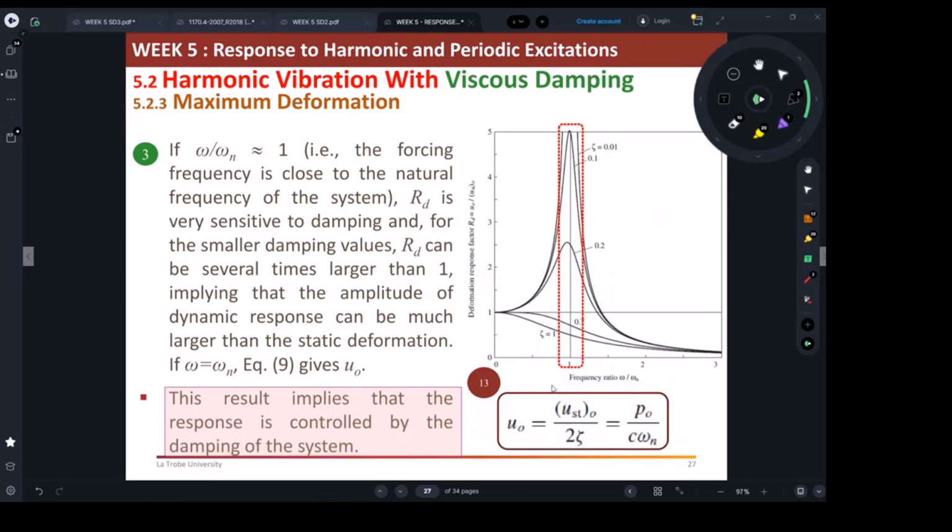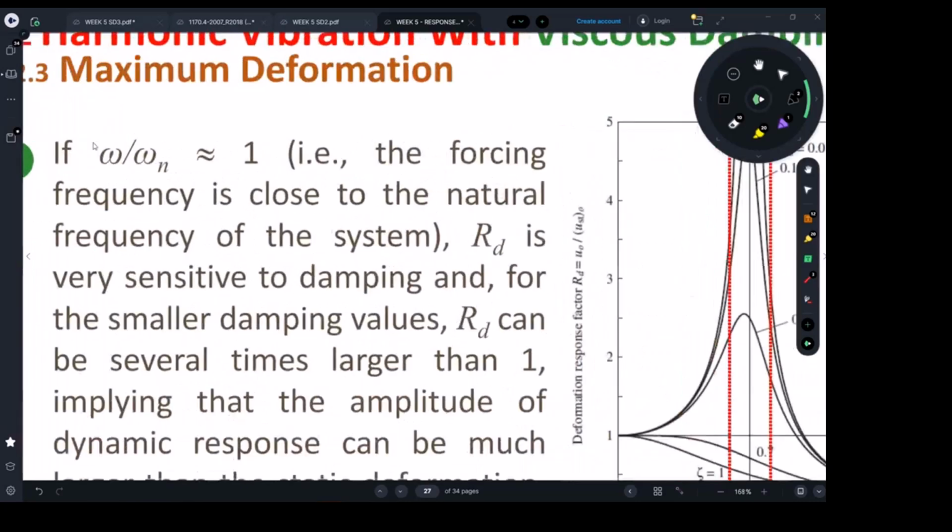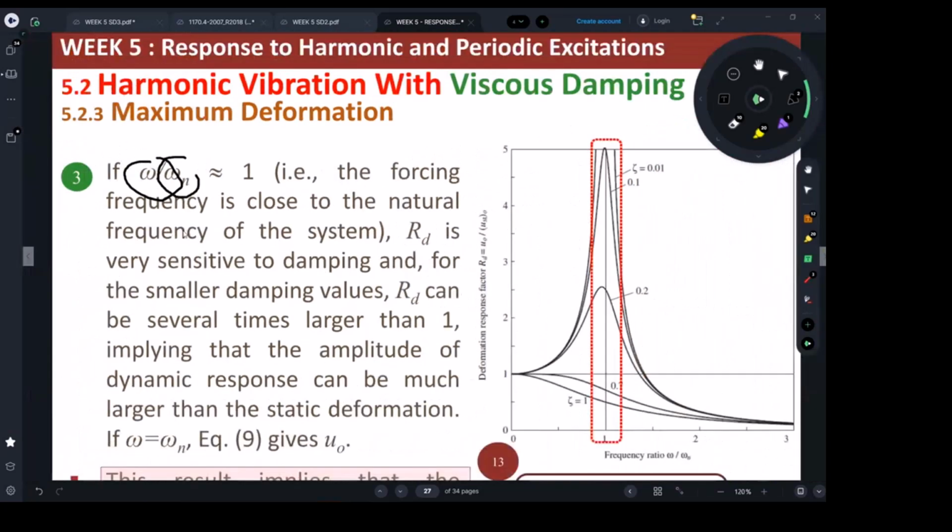So this third situation here, it is basically the resonance situation. And it's going to happen when your forcing frequency from the harmonic motion is the same as the natural frequency of the building. If you were really not lucky, and that's really, as I said, the glazing mechanisms, like the canopy, the glass. I'm not sure if you know really what I'm talking about. Can anyone tell me what I'm talking about? Try to find your picture.